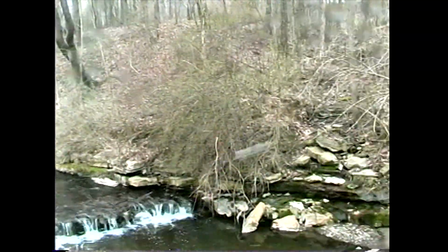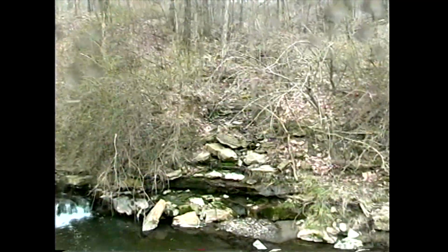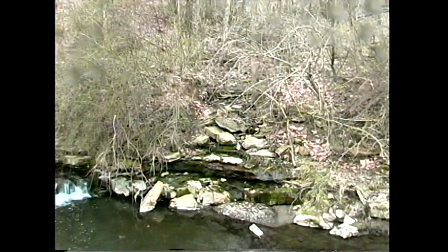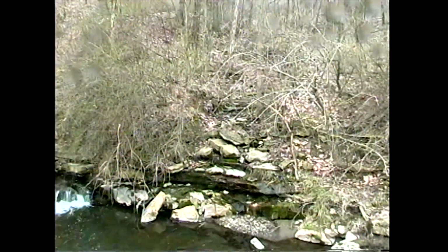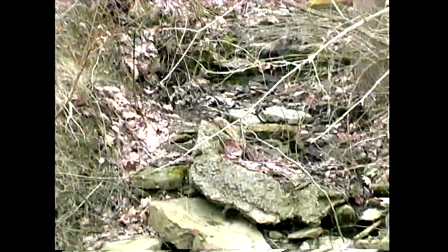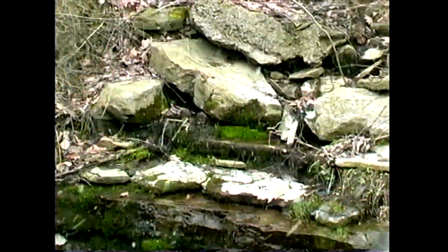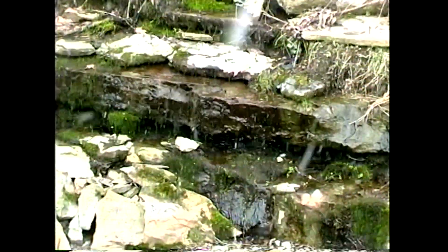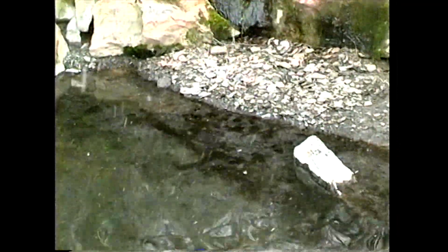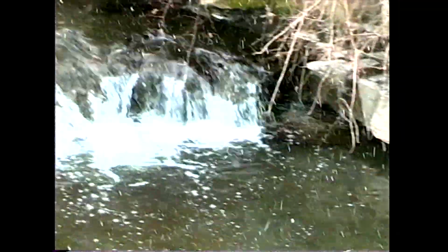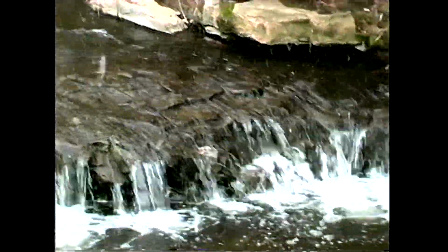And then in this tributary coming in, you can see how far McLaughlin Run has downcut, because this tributary should be at the same grade as McLaughlin Run itself, but because it's probably an intermittent channel, it doesn't have enough flow going through it all the time to stay at grade, and then this tributary's had to cut through this bedrock, which it doesn't have the stream power to cut through, where McLaughlin Run has just downcut tremendously, and you now actually have a waterfall situation, which probably was not an original situation. That has just formed to try and maintain that.